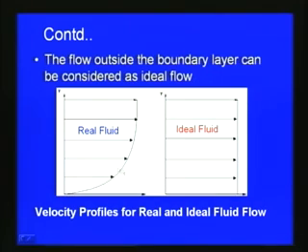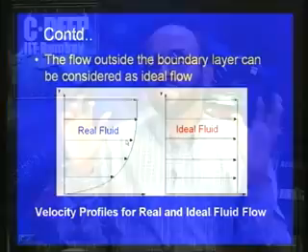If you can identify the exact location of the boundary layer, then after that we can approximate, even though it may not be 100% accurate, that after this boundary layer we have an ideal fluid flow or potential flow. So we can reduce the boundary of the problem and deal with it much more easily than when we consider the complete domain, such as the flow over an airplane or a space shuttle, where we would have to analyze a large domain.